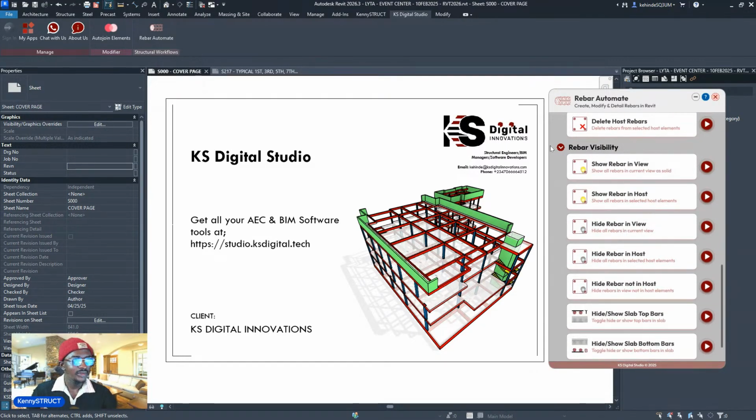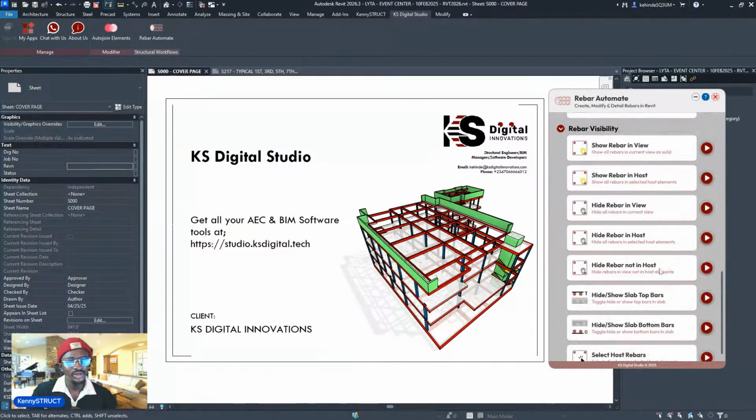And so you also have the rebar visibility category. It controls the visibility of your rebars in your views. You can show your rebars in a particular view, in 3D view or on a floor plan. You can hide them. You can show rebar in your host element. You can hide it in that particular host element. You can show rebars that are not in the selected host elements, or you can hide rebars that are not in the selected host elements.